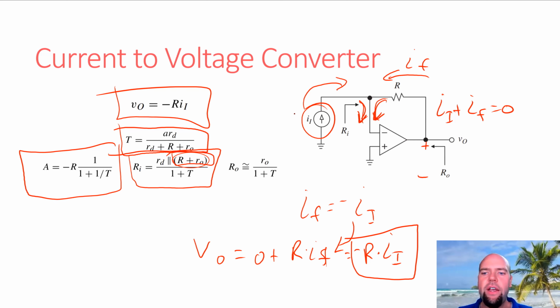The signal sent by your remote control is modulated at a specific frequency, and that can get filtered out later, and you'll talk about that in the next class. But the signal that's coming in is usually going to be something that looks like this, right? I think they're typically around 30 kilohertz or so is the modulation frequency of those signals, somewhere in the kilohertz range. And this can be a very small current.